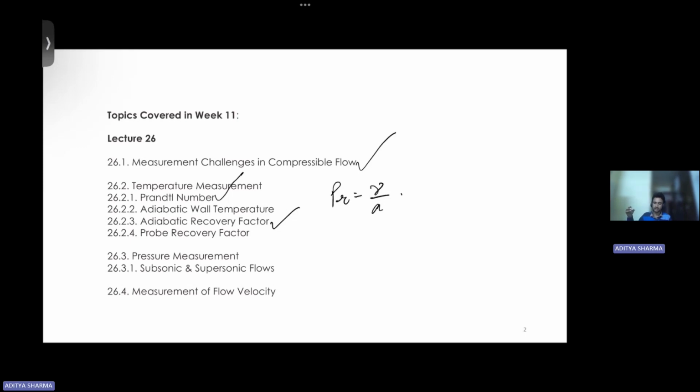At the start of this probe, we have a hole, and from there we get the stagnation pressure. At the walls of this probe there are other holes, and from those we get the static pressure of the flow, right? So we also call it the Prandtl-Pitot static probe.